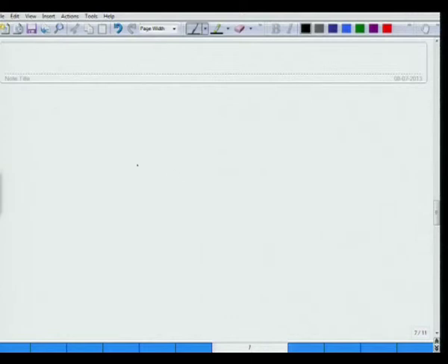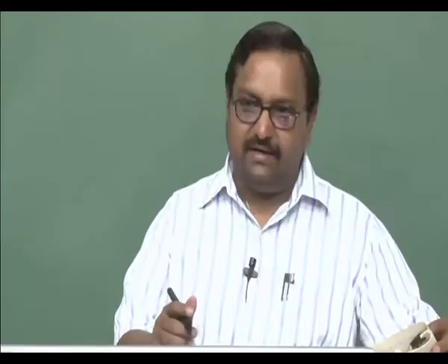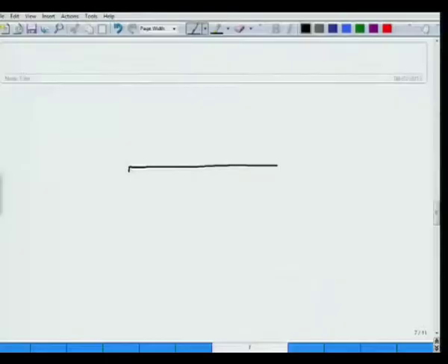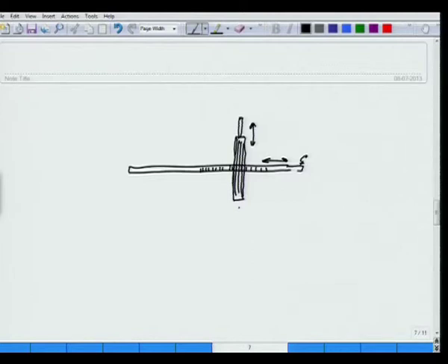The other one was a two motion selector, which required two electromagnets to work. One was a straight bar which is going to have gears on it. And then of course there is also a gear drive, so this can move upward and downward. This vertical motion happens because of another electromagnet depending on the pulse, and this motion happens because of this bar. So it will turn into rotation, and I can then connect a wiper.